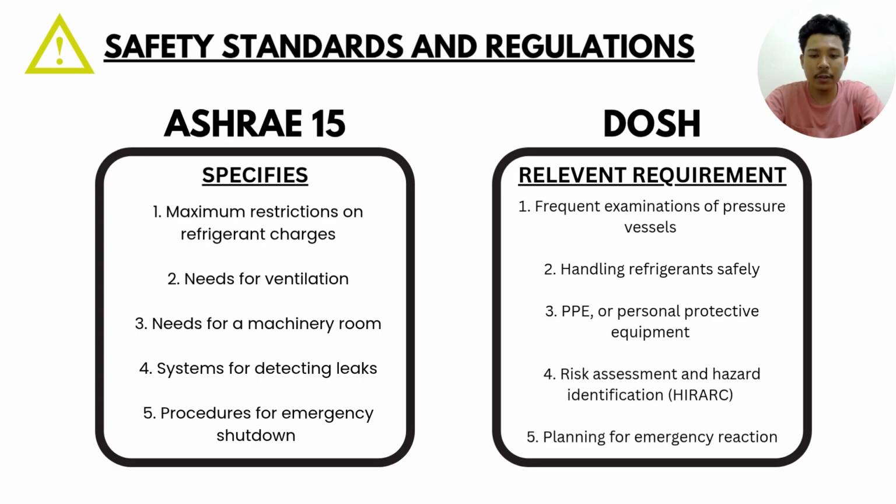This involves frequent pressure vessel inspection, safe refrigerant handling, and mandatory PPE for technicians. Crucially, DOSH requires a comprehensive hierarchy of controls assessment and a clear emergency response plan. Aligning with this regulation ensures our operation remains both safe and legally compliant.